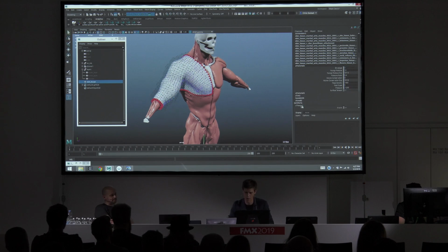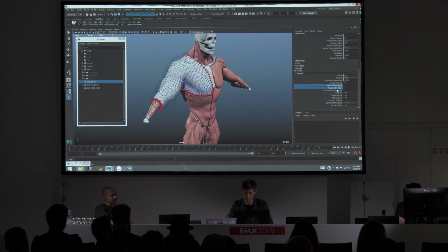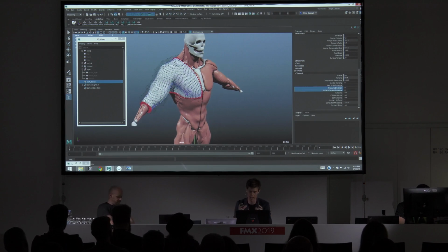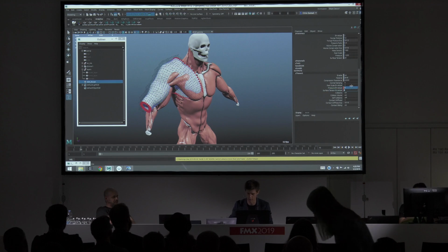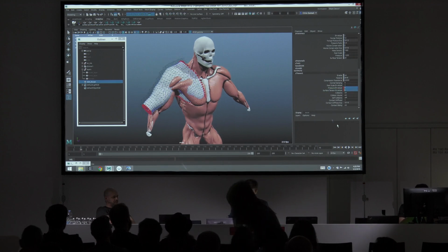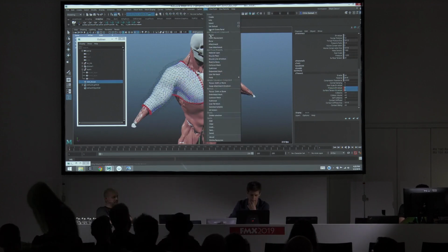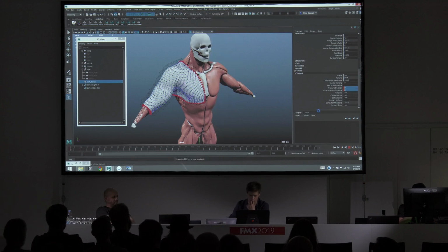And we want to ramp those attributes on over time. So we can do that here. Because if you have it just jump on the first frame, it's going to be too fast for the solver to catch, so it'll jump through the underlying stuff and you'll miss some collisions. Do 10 frames there. Cool.